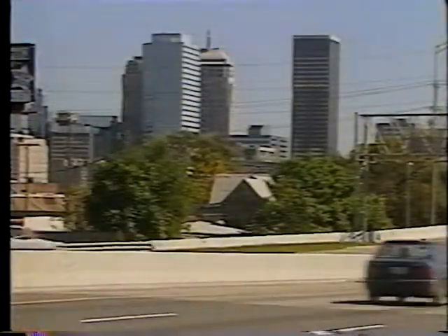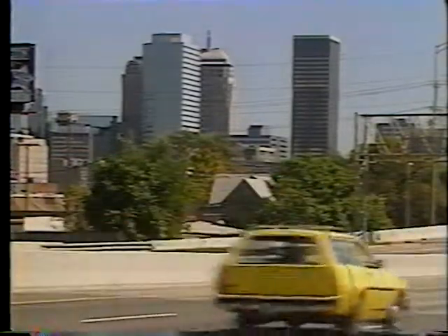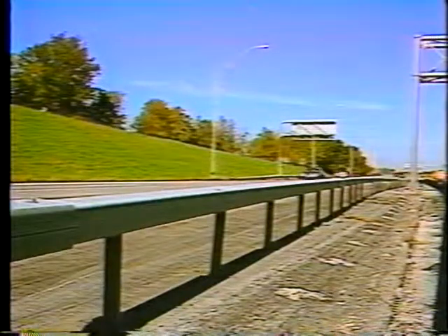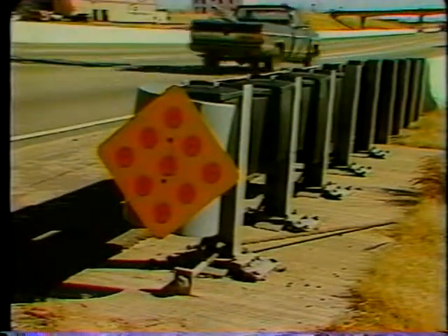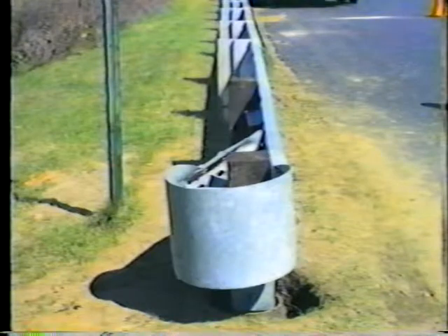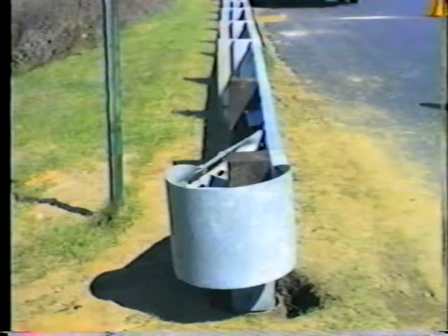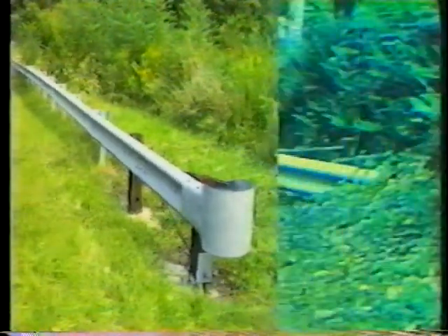Traffic barrier safety systems, whether they be roadside barriers, median barriers, or bridge rails, all need an end treatment. It makes no difference what type of barrier is involved. It can be flexible, semi-flexible, or rigid. All must have some form of end treatment. In this program, we'll look in some depth at 4 end treatments: the breakaway cable terminal, the flared and buried, the twisted and turned down, and the Sentre end treatments.